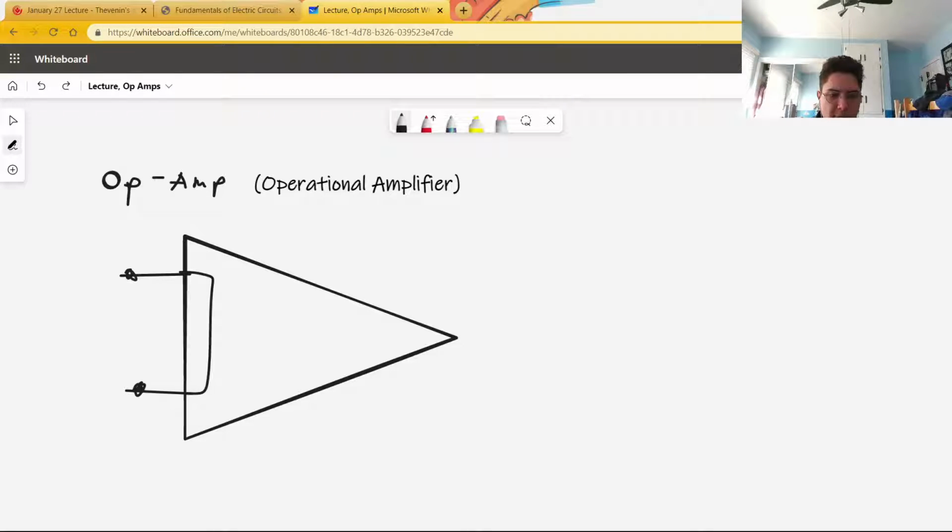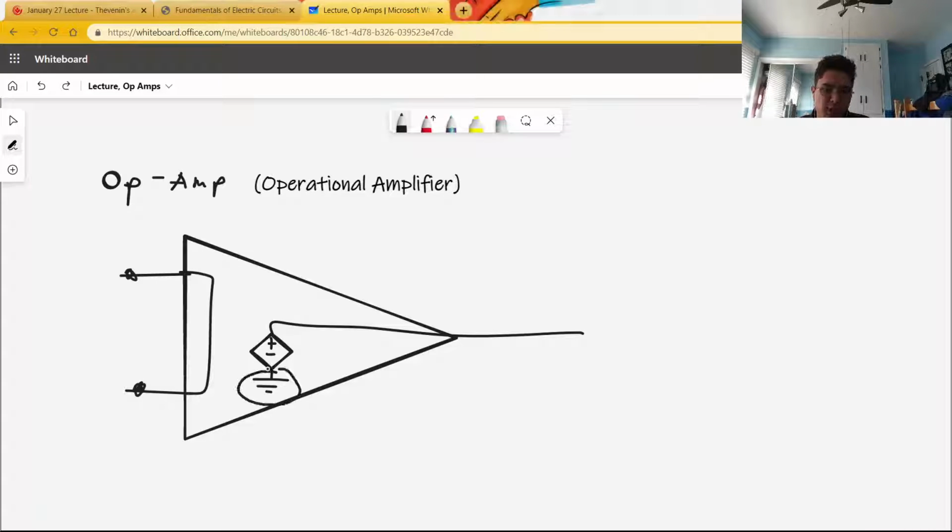However, in order for the op-amp to help maintain this voltage, it needs to create its own voltage, which depends on the voltage that it's trying to maintain. It creates this voltage with respect to a common ground in the circuit. Incidentally, that ground is also the reference for knowing the quote-unquote voltage at this point or along this wire. That quote-unquote absolute voltage is really a voltage with respect to the ground, and it is, in part, what is amplified by the operational amplifier.